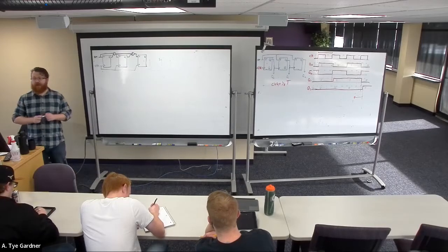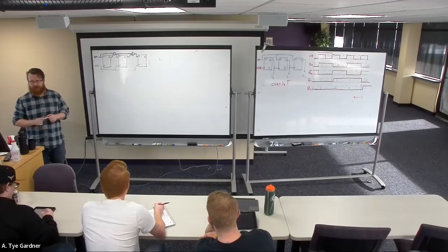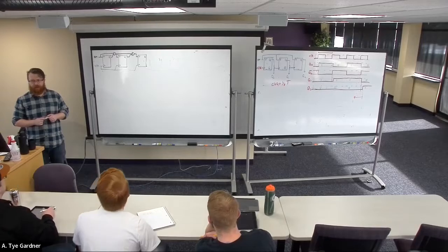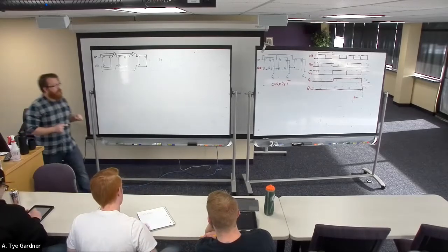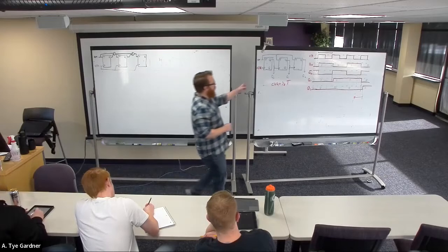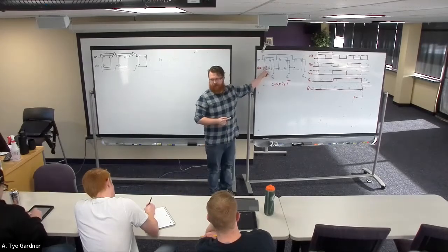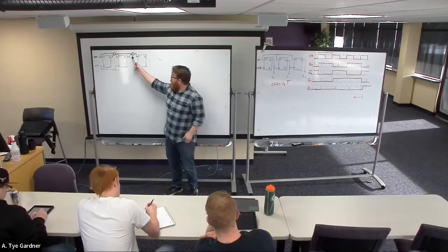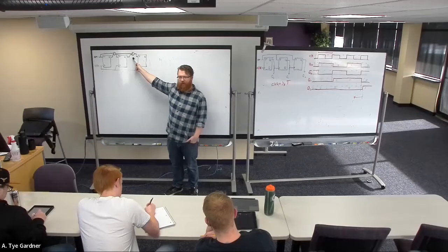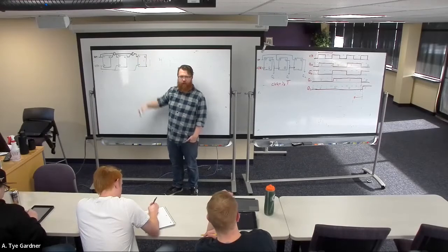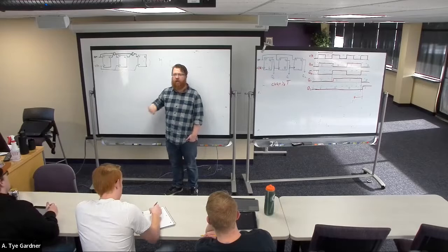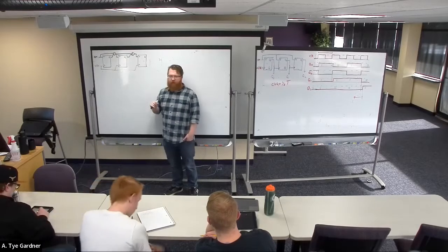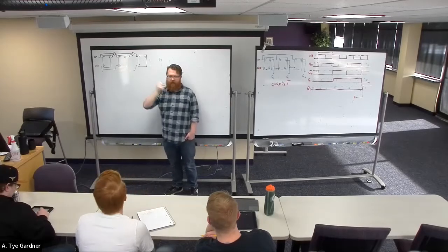What's more, this is actually a faster counter, we can run it faster because instead of having to wait on the delay of, let's say this was 8 devices, this would be roughly 8-ish times faster theoretically, because it doesn't have that accumulation of delays through the flip-flop path. It's just through the gates, the AND gates.